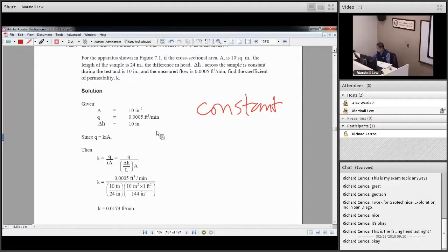As you can see, there's a wide range in permeability here, huge differences in numbers. This side is good drainage, here is poor drainage, and this stuff here is practically impervious. Obviously on the good side you have sands and gravels, this is gravel here, this is sands, and in this area we have clays.